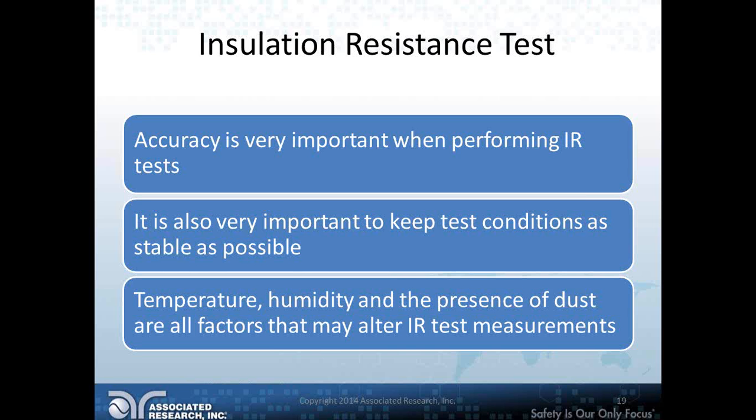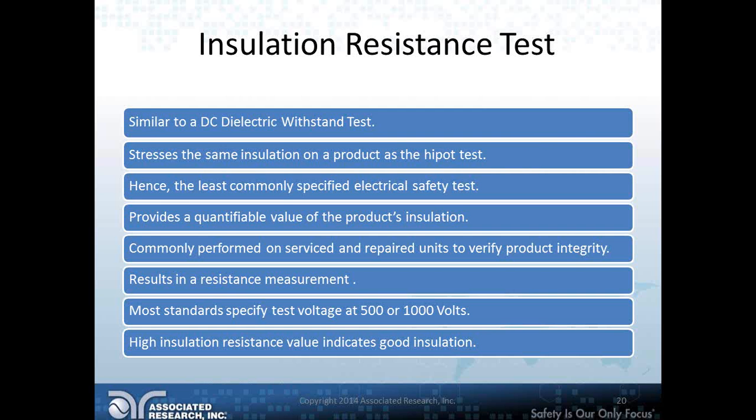Now, when performing an insulation resistance test, just like for any other electrical safety test, it is very important that the personnel performing these tests should be well trained. The reason being, this is a high voltage test and it produces some leakage current. Therefore, whoever the operator is, he or she needs to be well trained in using the tester itself and knowledgeable about the test.